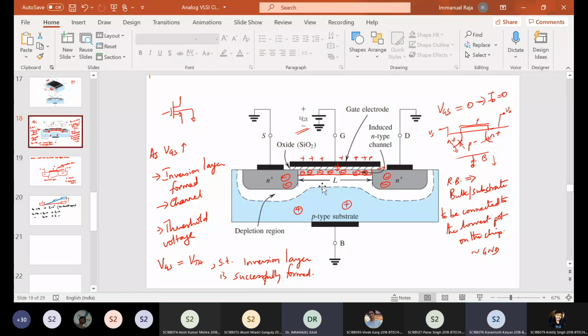When you say 180 nanometer technology node, the minimum channel length that you can put in that particular technology is 180 nanometer. The drawn channel length is 180 nanometer. But in a 180 nanometer technology, you can design a transistor with a longer channel length, even in schematics, as we will see when we look at current mirrors. In the same die you can have transistors with a channel length of 180 nanometer, and also 1 micron, or 2 micron, or 0.5 micron.